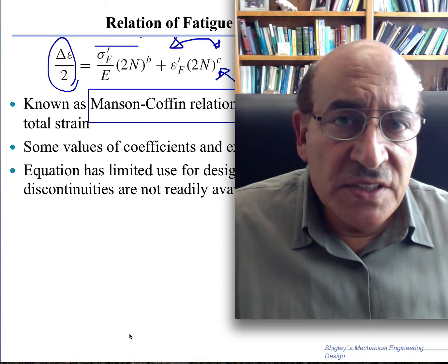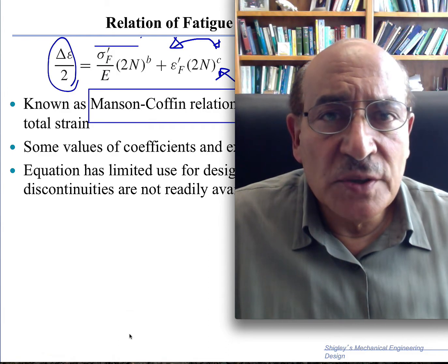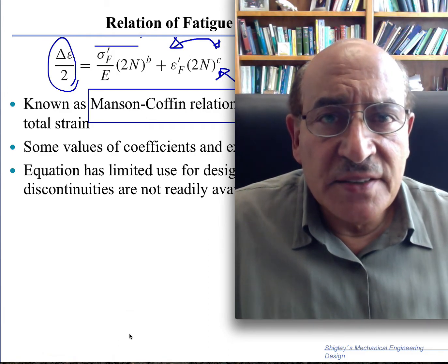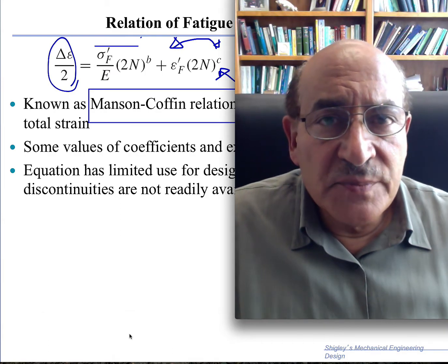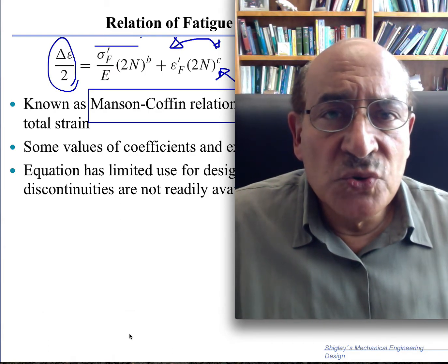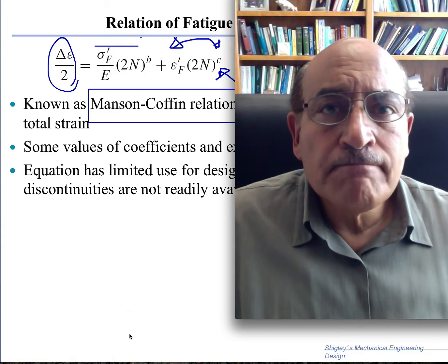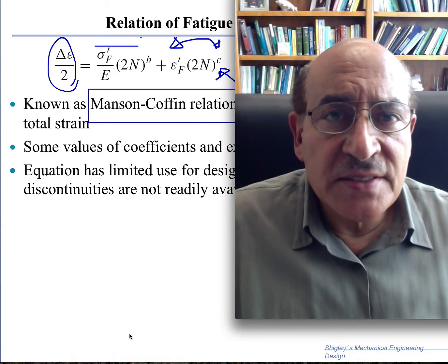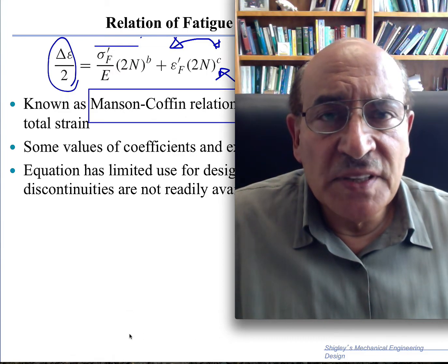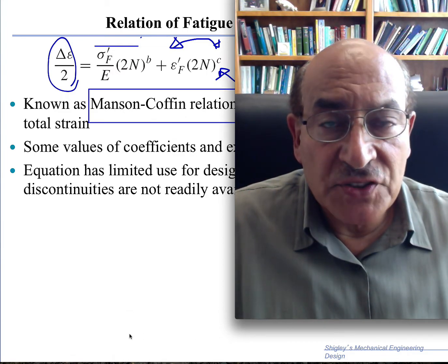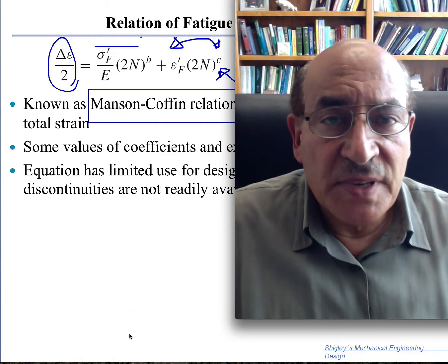And between these two, we can determine the local stress intensity factor of a crack in a given configuration, compare that to the fracture toughness, and if the stress intensity factor exceeds the fracture toughness, we determine that we have complete fracture by fast fracture, basically.